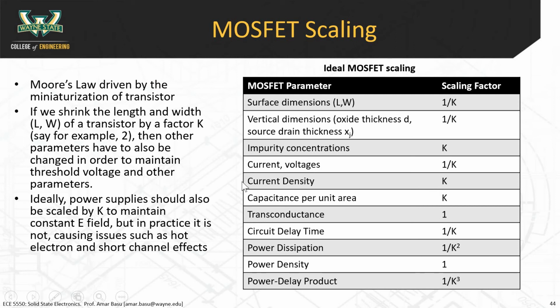The reason why the current density part is important is that if you make your transistors smaller by a factor of 1,000, which is what has essentially been done over the last 30 years, we've gone from 10 microns to 10 nanometers, the current densities have gone up by that much. There are more transistors operating, and you have smaller paths for the electrons to travel through.